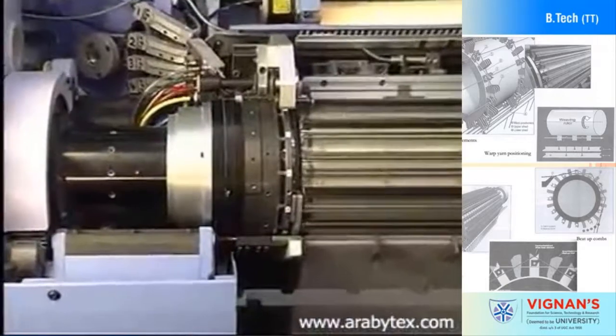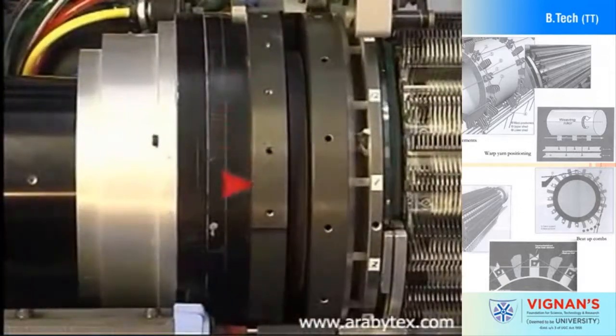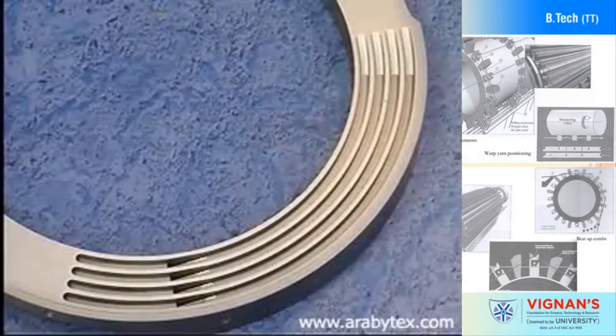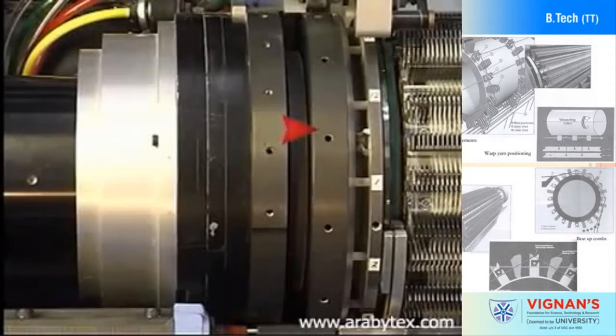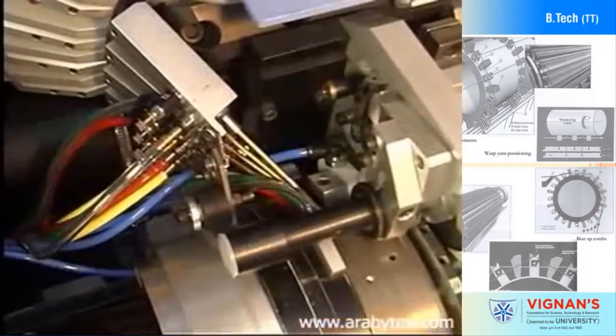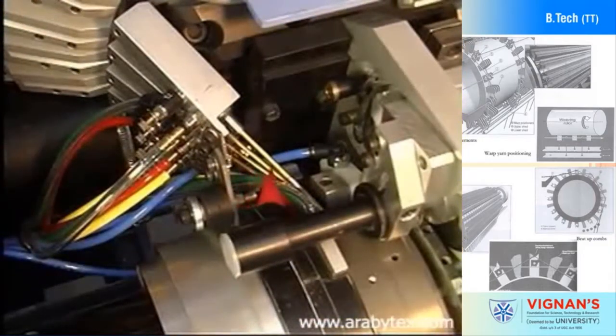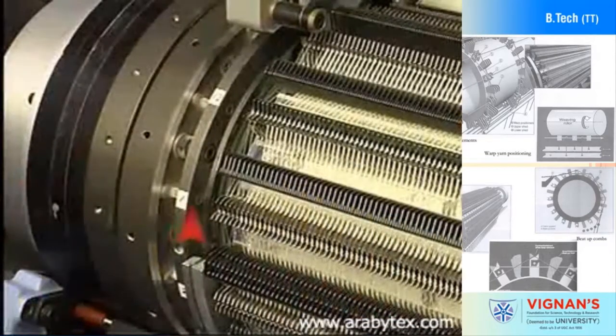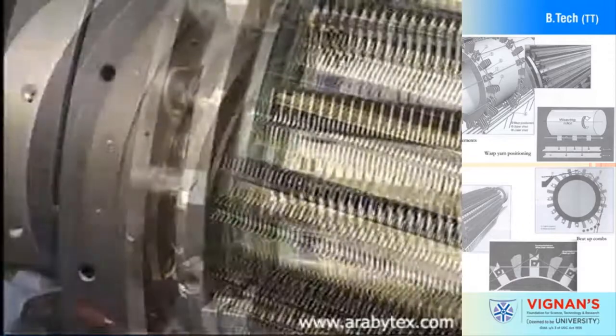2 main components of the insertion unit are the static disc and rotating disc. Both discs contain weft channels. There are 4 injector nozzles in the static disc and 12 weft nozzles in the rotating disc.